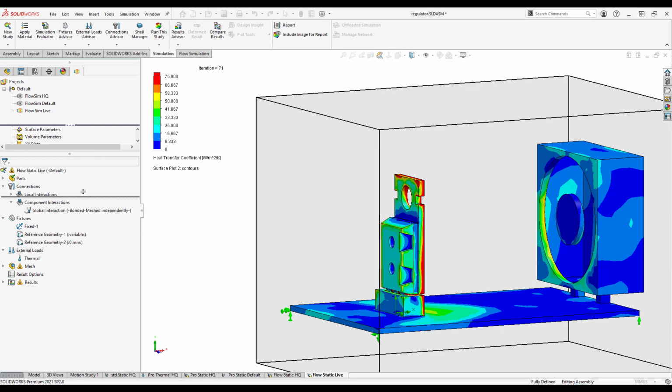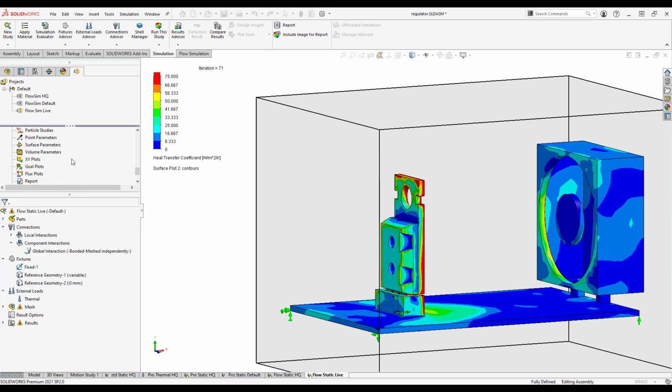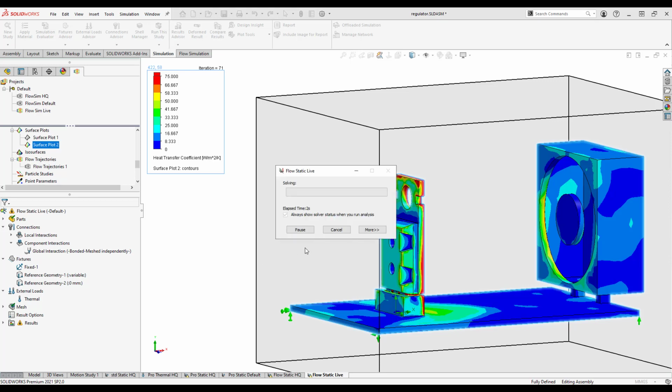By turning off friction and using bonded, we will lose a little bit of fidelity in the displacement results. However, the stresses in the chip to heatsink contact region that we've been analyzing should be about the same. Also notice that the runtime on this one is a lot faster. Instead of taking 78 seconds like it took on my machine earlier, this time it only takes about 5. That means it was about 15 times faster in this case to run with a bonded contact.